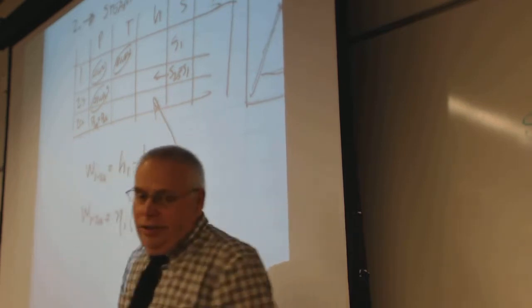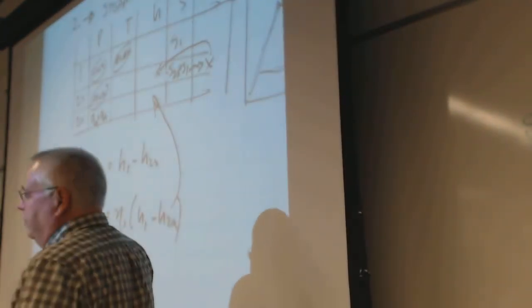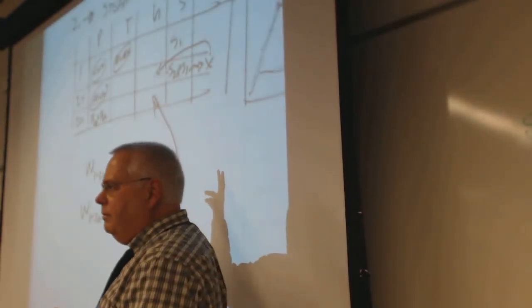So I guess I should say, let me draw it like this. You use the entropy value to find X. Use the X value to find H. That's really how that works if you're in saturation. Does that make sense? Kind of what we're going for here.